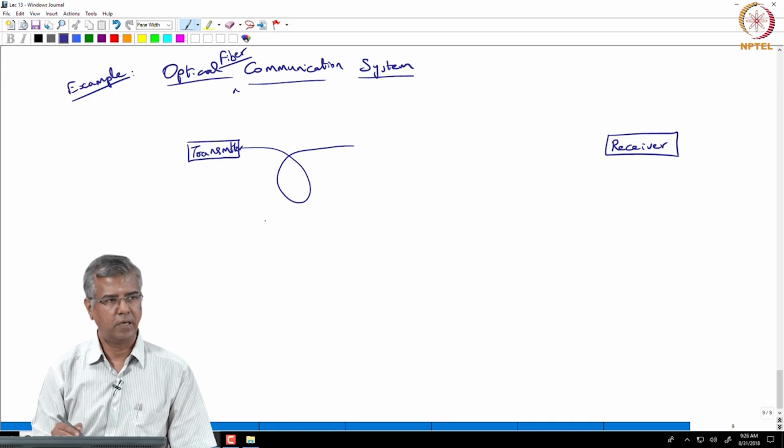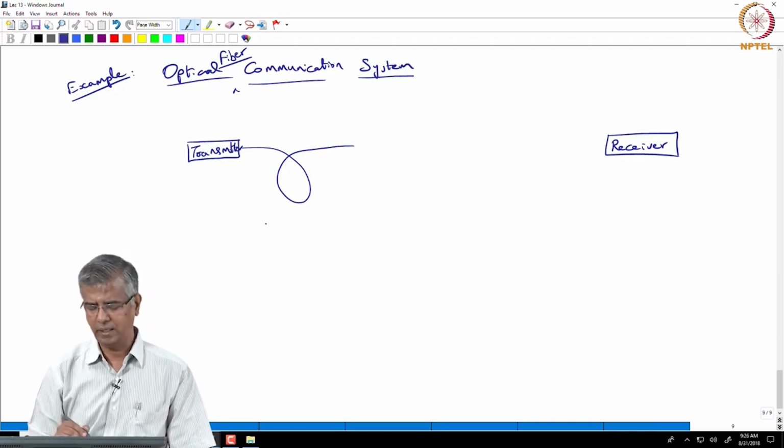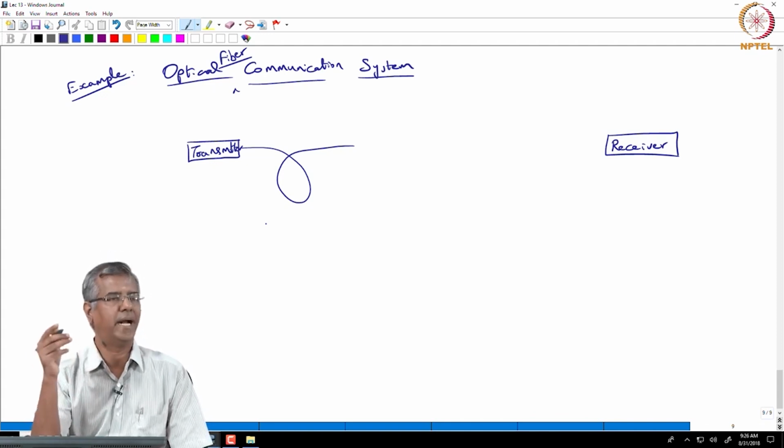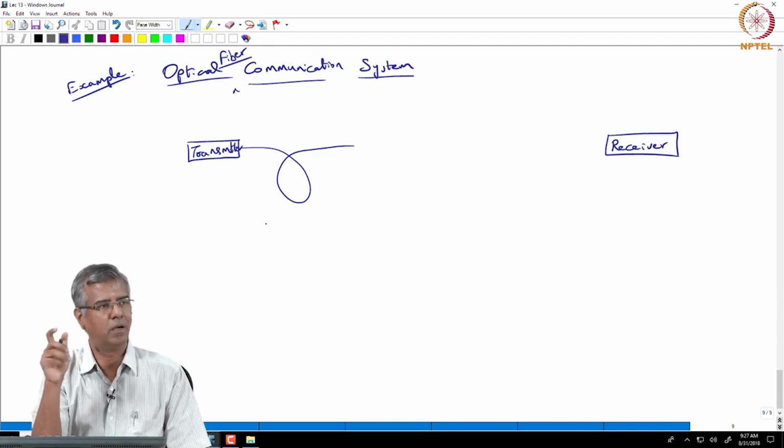Clearly when we are using an optical fiber, we go through a long length of optical fiber. That fiber has some inherent attenuation. What causes this attenuation? There may be some scattering happening in the fiber, something called Rayleigh scattering, because the optical fiber is made of silica glass, but it's amorphous in nature, and there are a lot of density variations in the glass.